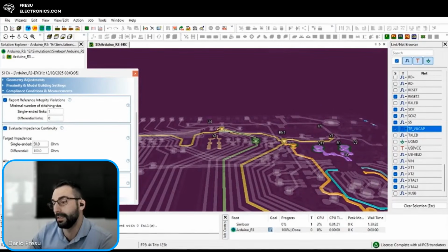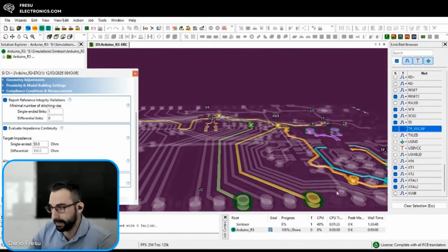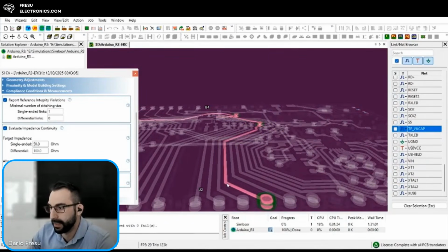And the other thing that I can check in here is the crosstalk noise. Here I can select how much local coupling threshold I want. So for example, here I select 10 millivolt, and I'm going to check between this net, the net that I'm selecting here, how much crosstalk there is going to be. So how much coupling of the signal from one net to the other. If I have a signal in here, how much of the signal is going to couple to this?